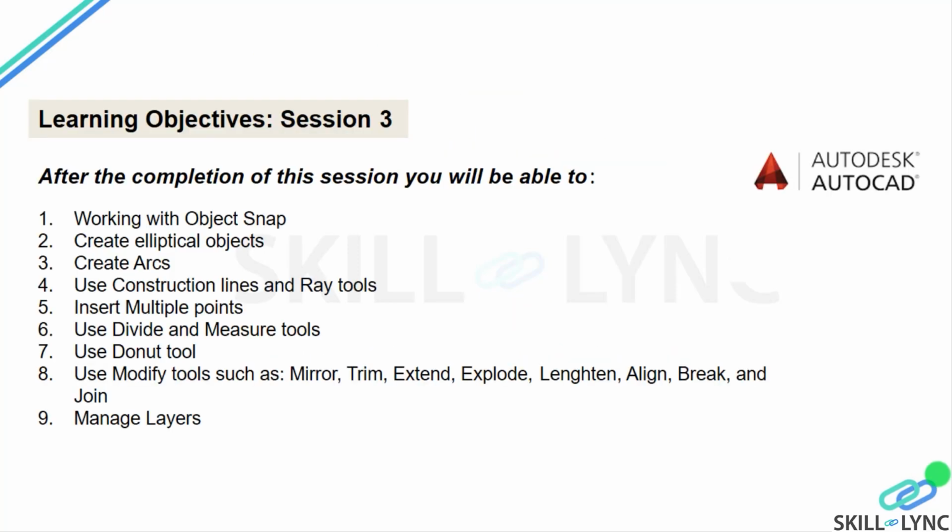So in this week we are going to cover some of the very important tools and options like the object snaps, arcs, construction lines, multiple points, and layers, in fact. And there are so many modify tools such as mirror, trim, extend, explode, lengthen, align, break, and join.